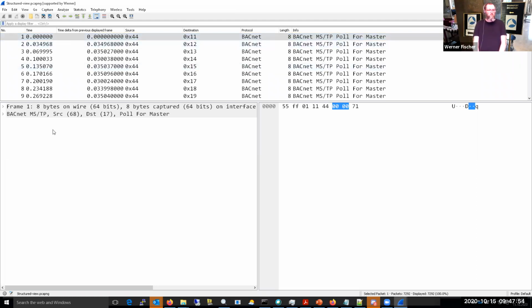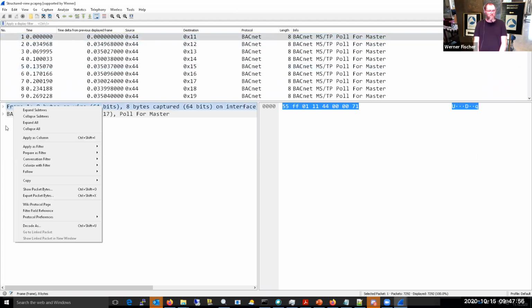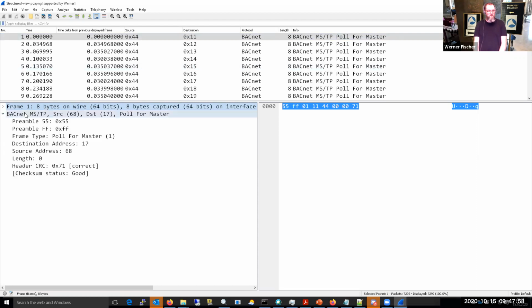So there's BACnet, yeah. You see, no Ethernet header. There's only BACnet, MS/TP source and destination here. Okay. No Ethernet, no IP, no IPv6, no ARCnet. So different encapsulations, I call it, yeah, for BACnet are used, and Wireshark is able to represent most of them, yeah.